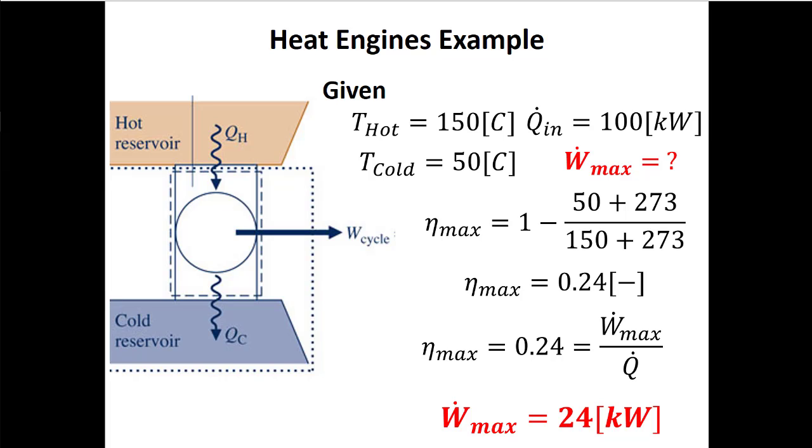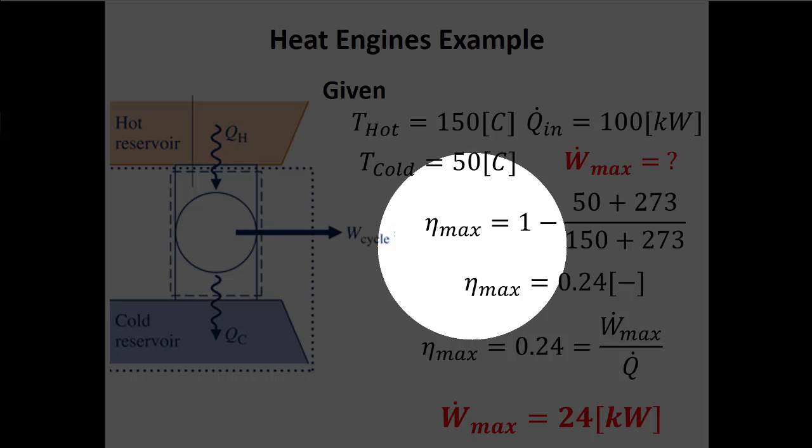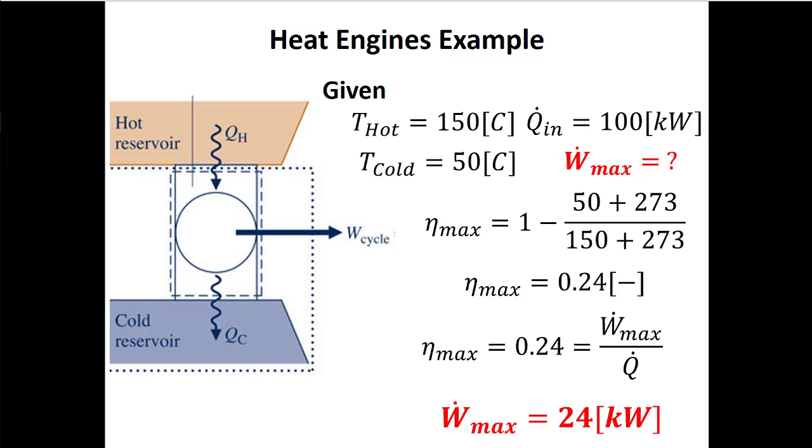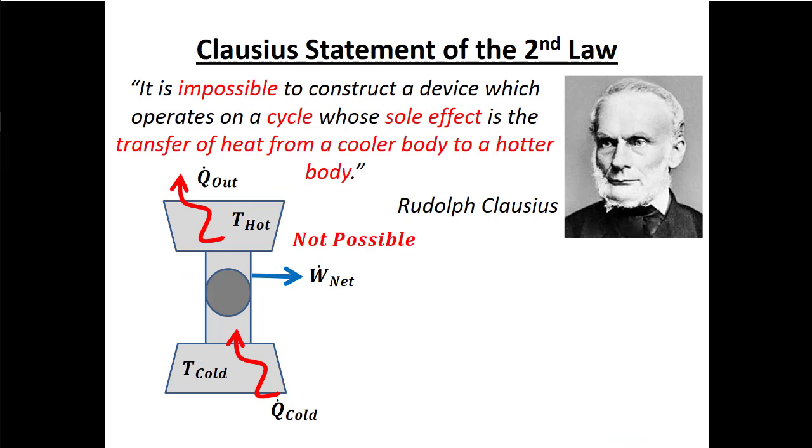This is another cool thing about having simplistic models like this. So we won't go through it too deeply, right? But I'll tell you that there's a couple things that you could figure out. If you wanted to increase this maximum thermal efficiency, and it's 1 minus T cold over T hot, you've got two levers, T cold and T hot. You could tell me two things that we could do to improve the maximum thermal efficiency here, right? But we won't go into it. We'll talk about it a little bit later. But that's the nice thing about a simple model like this, it shows you what your variables are. So how could we get a better thermal efficiency, right?